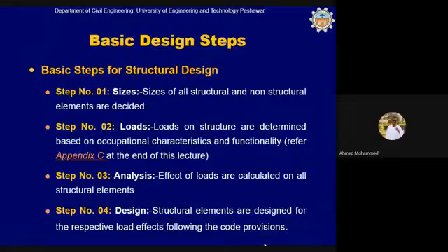What about roofs and floor? If a wall is a load-bearing wall, if a wall is part of a load-bearing wall system, just like in our residential buildings, in homes, where the slab is supported on walls, then the wall will be a structural element, not a non-structural element. Okay, that means by non-structural we mean those elements which are not transferring any loads. Yes, you're right. Okay, that's it. Thank you, sir.